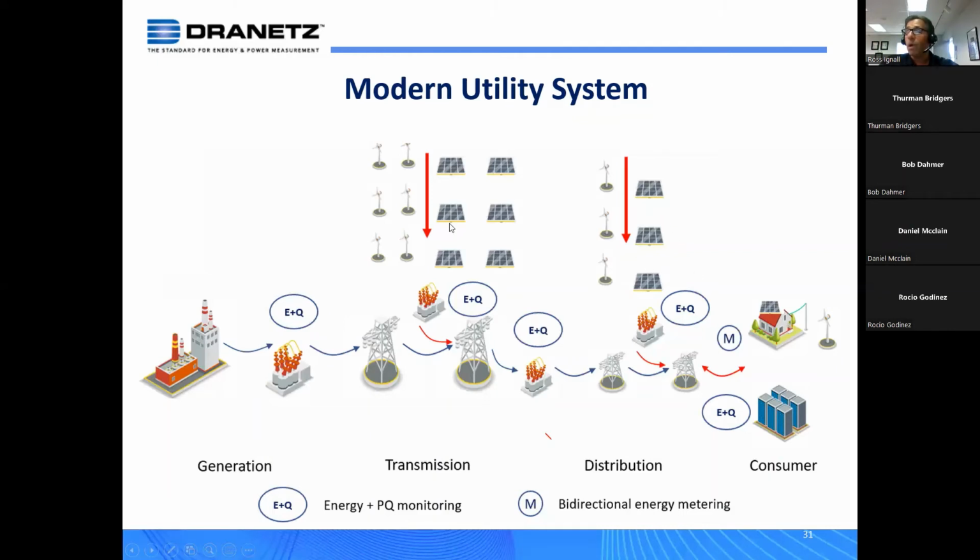but also along the line, going up closer to the typical transmission methods, you can have the wind, you can have the solar. So these very high power inverters are transforming this DC into AC and interconnecting with the grid. Well, there are concerns of their frequencies traveling throughout this grid, creating those Supra harmonics, these higher order harmonics that cannot be measured by the typical power quality meter as specified by 61000-4-30 today.